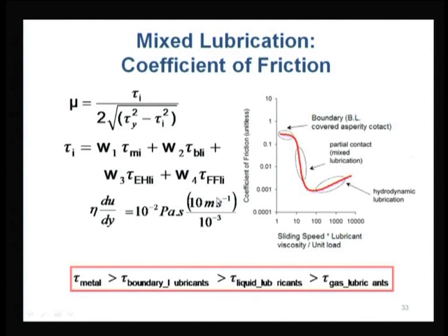And velocity, if I can roughly estimate, maybe around 10 meters per second, that is a relatively high velocity, and the separation between the two surfaces is maybe around 10^-3, or say 1 mm. If I go ahead with this calculation, what we are going to get is something like 100 Pascal.